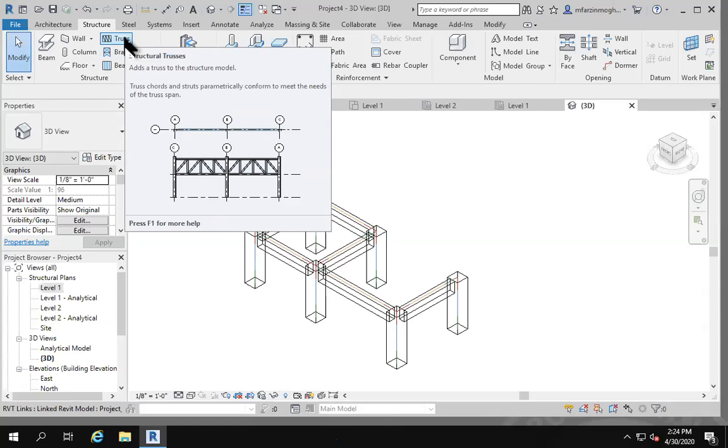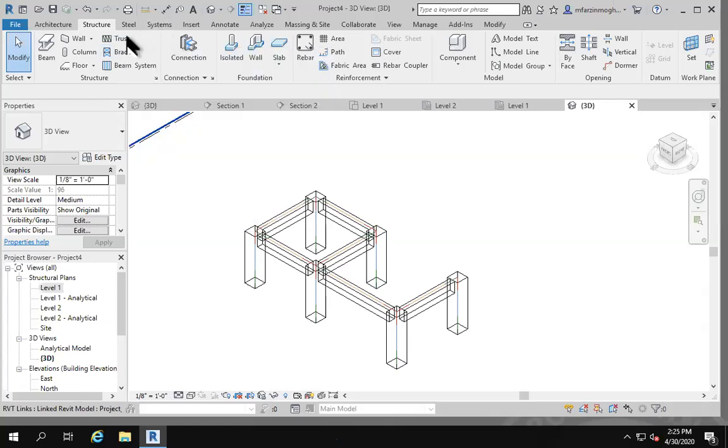It's not that different. The only thing you want to pay attention to for the truss is that the truss system gives you flexibility to have a larger span. Maybe in places where you have an atrium, or for example an auditorium, you put the truss system in order to open up the space, so you want to take advantage of the truss system in those areas. It's not going to be much of a difference in terms of usage in Revit, but in terms of the architectural capacity it gives you, there's a huge difference in terms of span size.